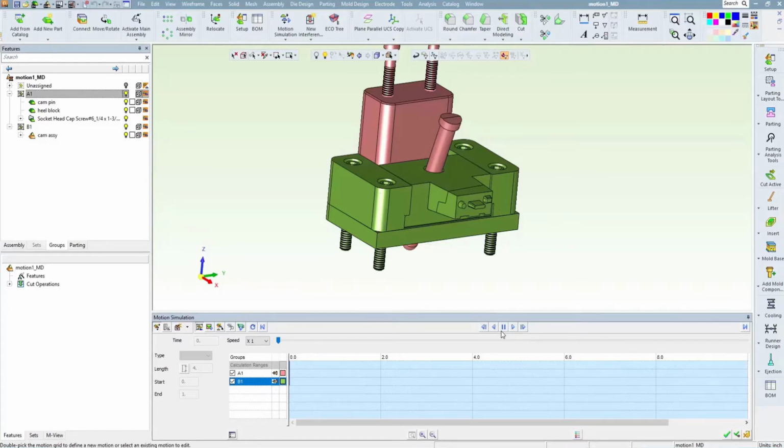There is a lot to talk about in this dialog, but first I should finish up with rule number 1, which was to group the parts that move together. What I have so far is not correct. The Gibbs and wear plate do not move in relation to each other, but the slide part does, so it must belong to its own group. Any part that moves independently must belong to a separate group.